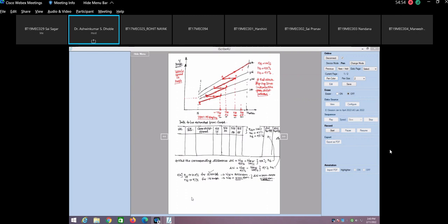So what is the conclusion? What you have to do is prepare the table, prepare these kinds of graphs, and find out the delta N required for gear shifting. In gear shifting, with 100% efficiency, how much engine RPM was there when you shifted gears? Now if 97% comes, how much additional RPM is required? 97, at 95. And finally you have to write down the conclusion.